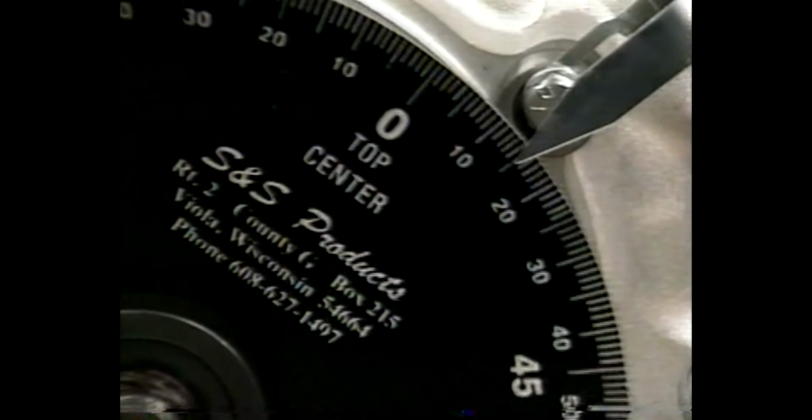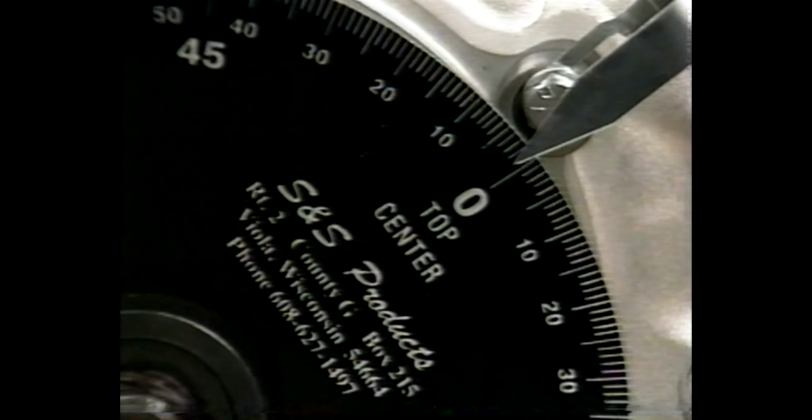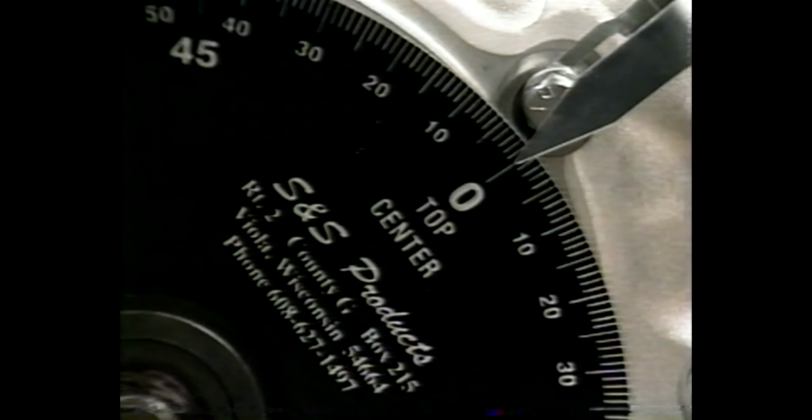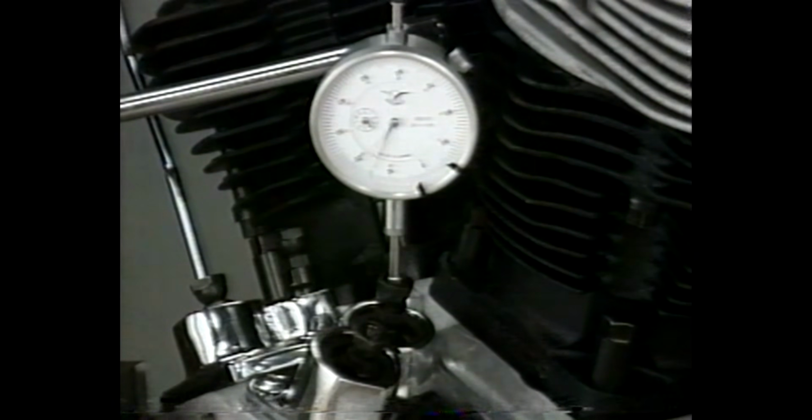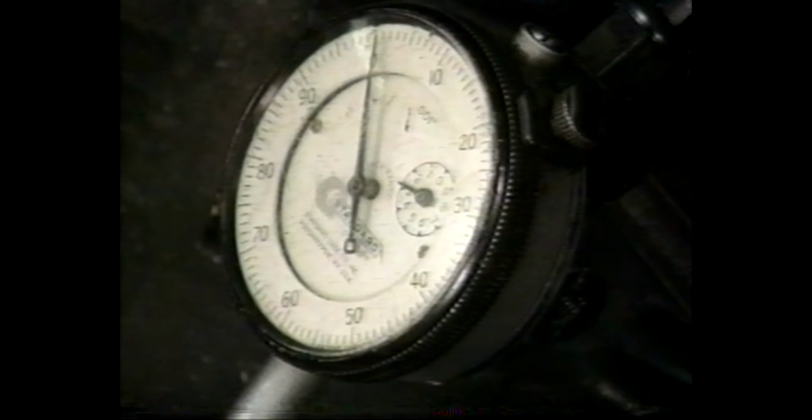To degree our camshaft to our engine, we must use the degree wheel that we previously mounted and zeroed to top dead center when measuring the duration, the lift, and the other physical characteristics of our camshaft. We place our dial gauge in the center of the front intake lifter, using the same techniques we used earlier when setting up the gauge on the front exhaust lifter. With our dial gauge securely in position, we rotate the cam forward until the lifter is on the heel or base circle of our front intake cam lobe, and then zero our dial gauge.